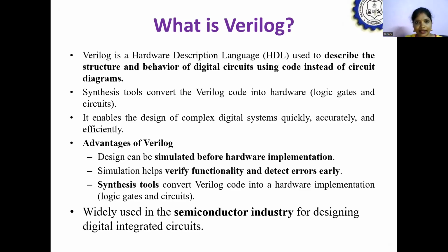If there is any error, again we modify the code and perform the simulation. Once the design passes all the simulation tests, next we use the synthesis tool, which converts the Verilog code into the hardware implementation, that is in the form of logic gates and circuits. Because of these advantages, Verilog is widely used in the semiconductor industry for designing digital integrated circuits.